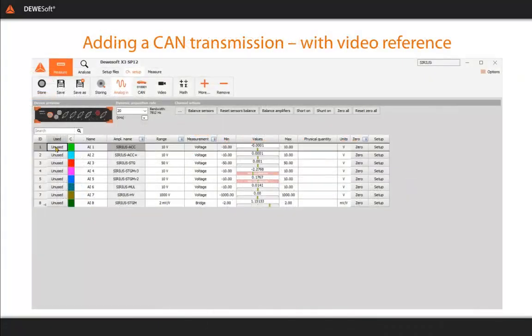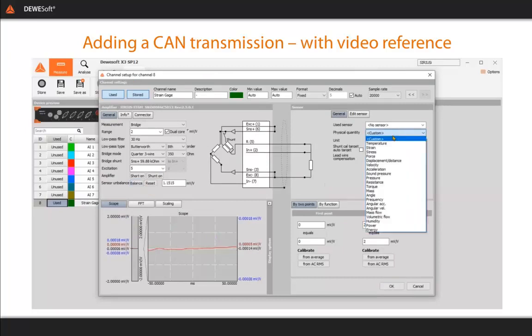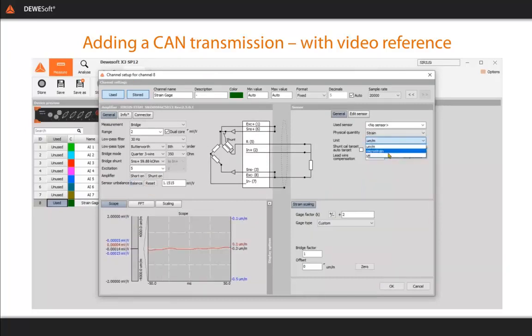A very powerful tool in the developer's arsenal is the ability to broadcast on CAN. This is particularly useful if you are testing the behavior of a sensor which you plan to add to a network. It is also a very useful tool if you want to make peripheral data available to devices on the network. In this example, we start by adding our sensor, as we did before.